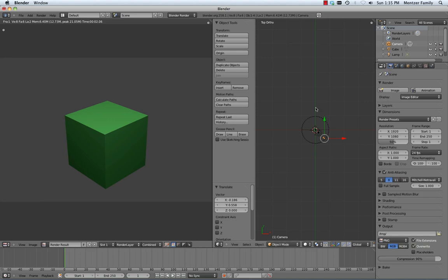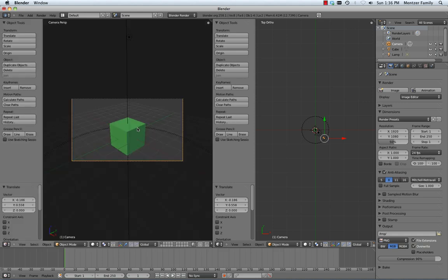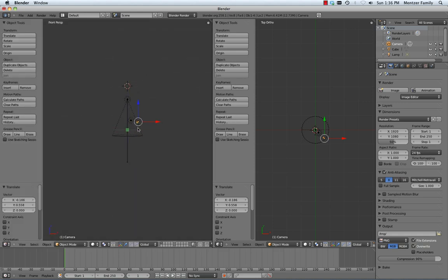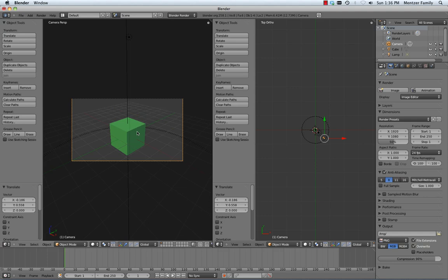And that'll do it for giving you a quick overview of how to set up basic lighting, apply a basic material, and move your camera around to give yourself a render image in the frame that you wanted to see, and previewed through hitting the 0 key on your numpad. 0, again, is what brings up the view from the camera in your scene.